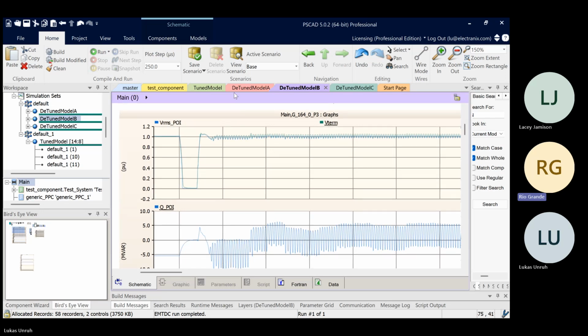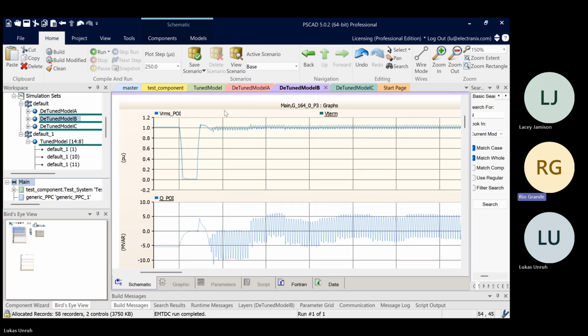It's a bit of a different story when we're talking about voltage droop values in a plant controller or something like that. But this is very much in the guts. A good general rule is, if it's in the plant controller, you can probably tune it. If it's something at the inverter level, you probably want to ask for confirmation. Even if it's clearly labeled inverter level voltage ride through gain and you know exactly what it is, you probably still want to confirm with the manufacturer because that gain could have effects on other capabilities.